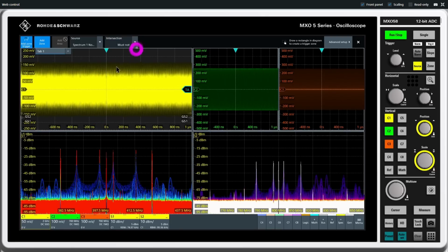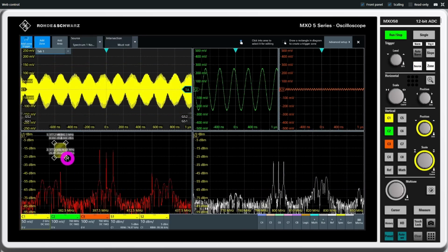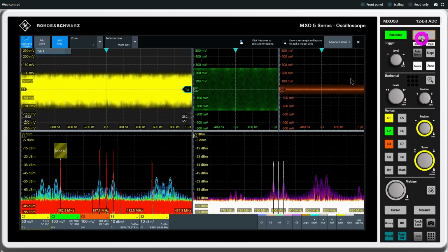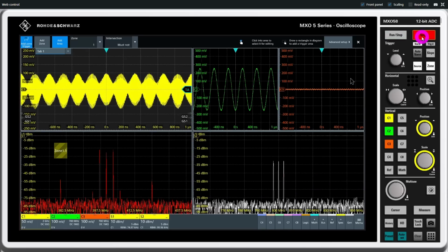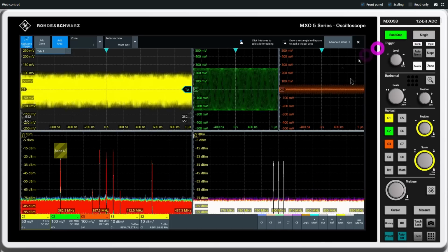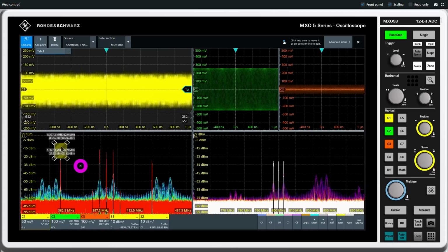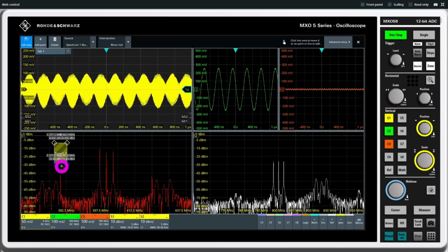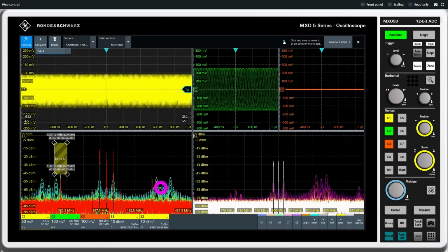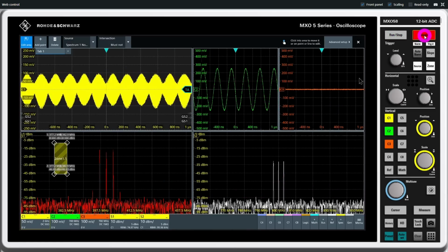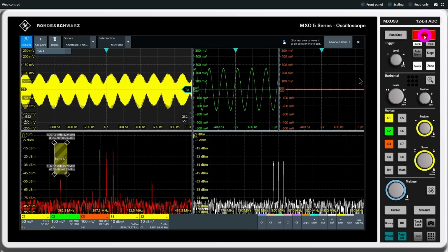So how can I do that? Well, now I'm going to choose a situation where the square I'm going to draw should not intersect the waveform. And I'm going to draw a little one over here and leave it like this. Look at that. Every time I do a single trigger, that waveform can never be in that zone, so the amplitude is smaller. But now I can also select it and push it further down by selecting this edge and bringing it down, and see how low I can bring it. Now, every time I trigger that, I see amplitudes that are even smaller.